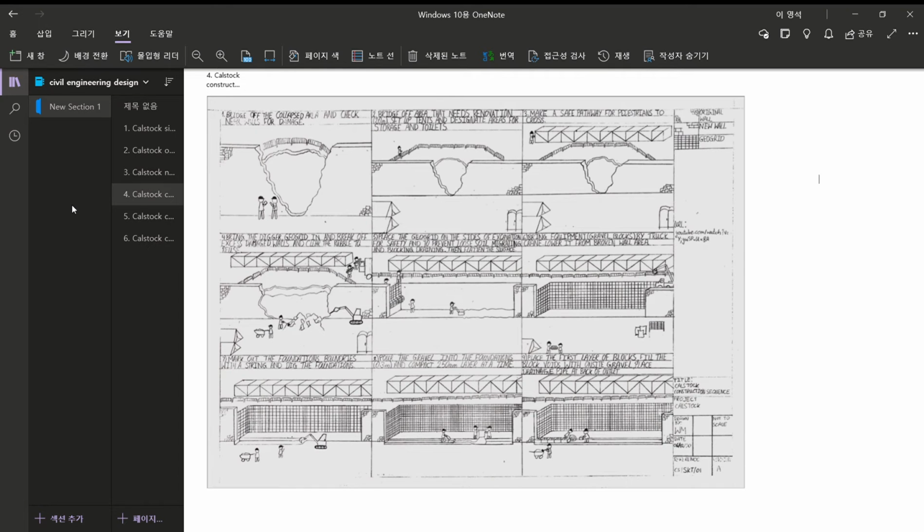Then, using a string, mark out the boundaries for the foundation and start digging the foundations, which are 300 millimeters deep and 600 millimeters wide. Once the foundations are dug out, pour the gravel into the foundation and compact it using a compactor. On the top of the compacted gravel, the worker will start placing the first layer of blocks and fill them up with gravel to increase the wall's weight.